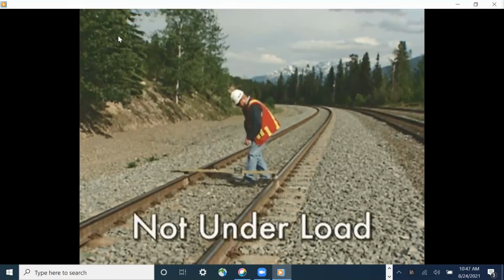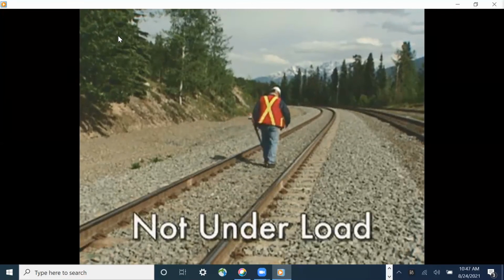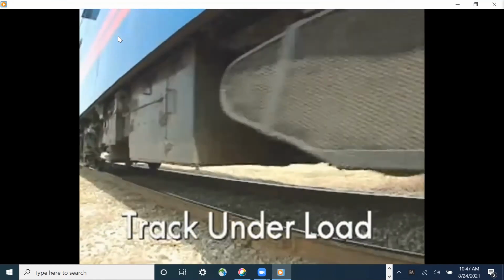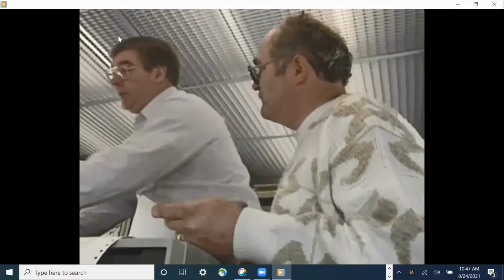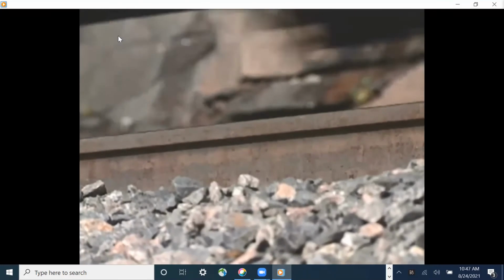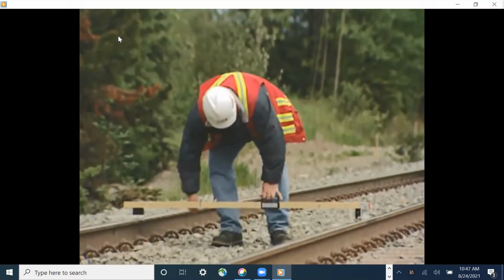Yes. Inspection that is not under load can provide a lot of information about the relative condition of the track structure. However, measurement of track conditions under load is done by a track geometry car and takes into consideration the many forces that affect the track structure. Regardless of how deviations are measured, any amount of rail movement that occurs under load must be added to any measurement taken on unloaded track.